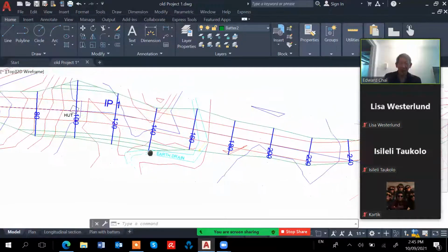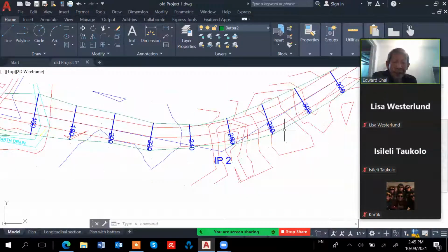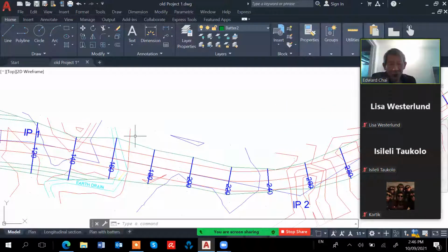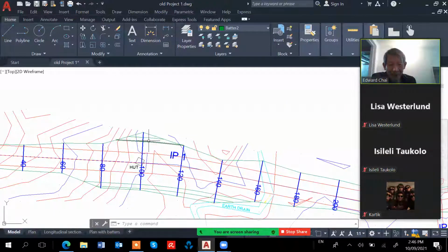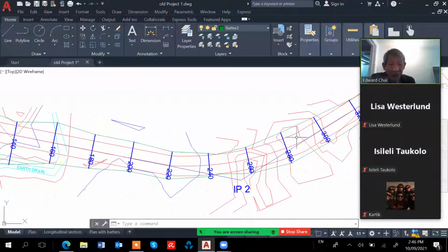Okay, so we do this for this side, and then this side here for my case for this joint. This one looks a bit too wide, we don't need the berm. Yes, because this one the fill is a lot, so you get a berm here. But in this case here looks okay. The green line doesn't look that wide.